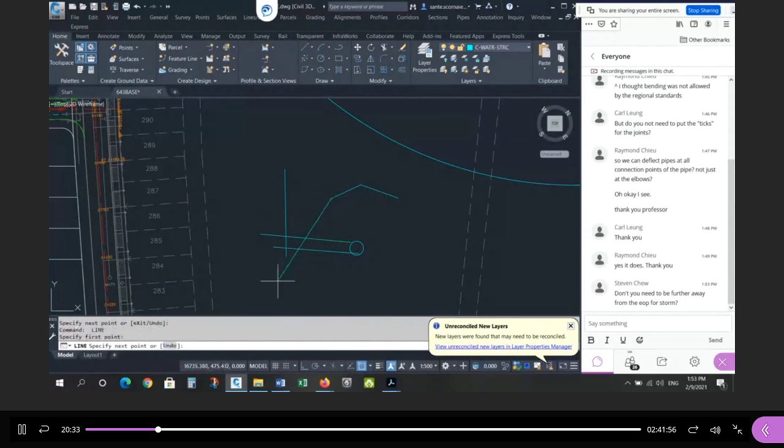And you can dig down. This would be the line of influence, 1 to 1 or 1 to 2, so that you can get down to this depth. And that's why you want to maintain it. You don't want to put the maintenance hole right on the edge of pavement. Otherwise, if you dig straight down, this pavement is going to fall apart. So 3 meters is typical. If you stay away by at least 3 meters, you should be able to uncover this pipe, connect to it, put a structure in, and still have a stable slope to hold up the original road.